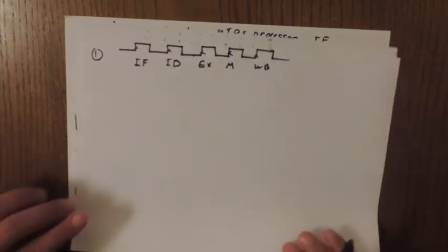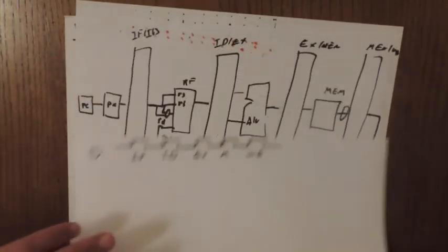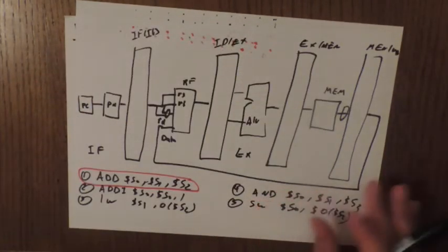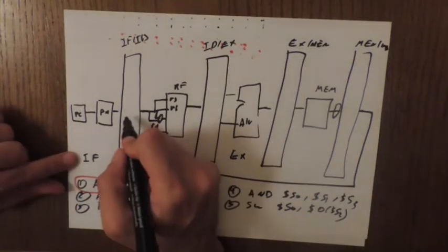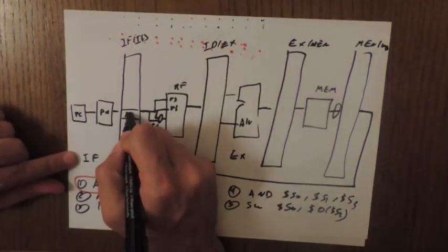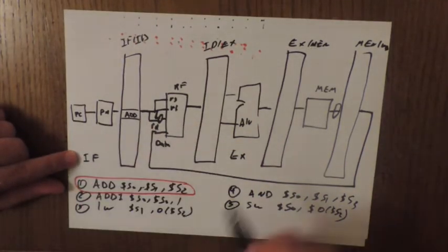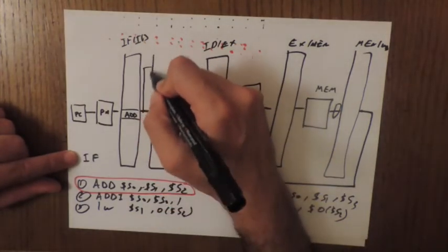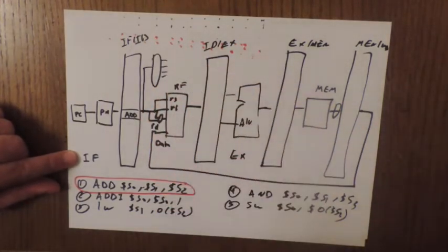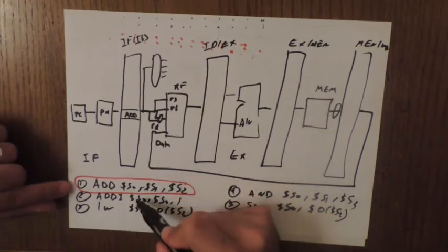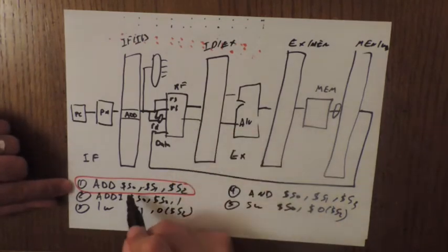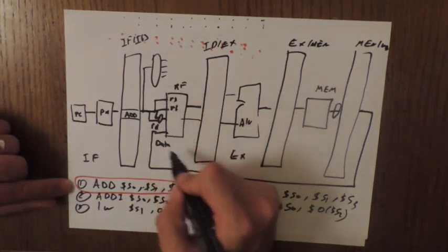So first, in the IF stage, what I do is I actually fetch the instruction, so that the instruction here will be the add instruction. Then, of course, here we have the control lines. Then I get S0, S1, S2, I get them decoded.